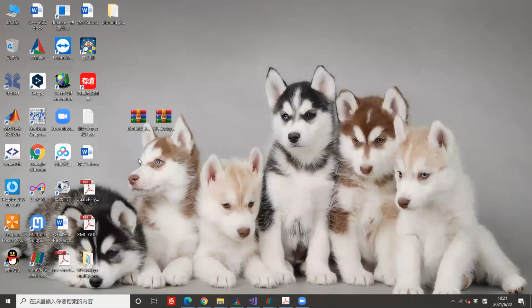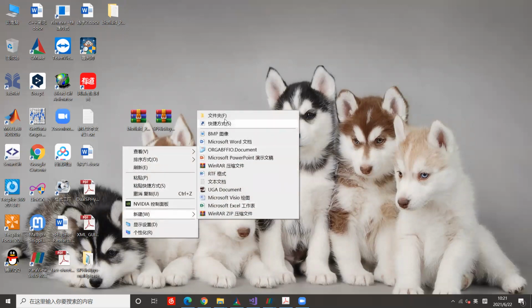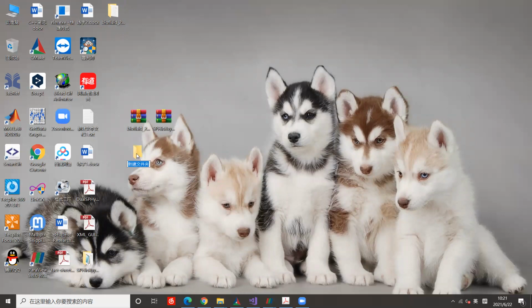So next, we should use CMake to build the SPHinXsys. Before this, we should create a new file folder named as you like. I named it SPHinXsys build.